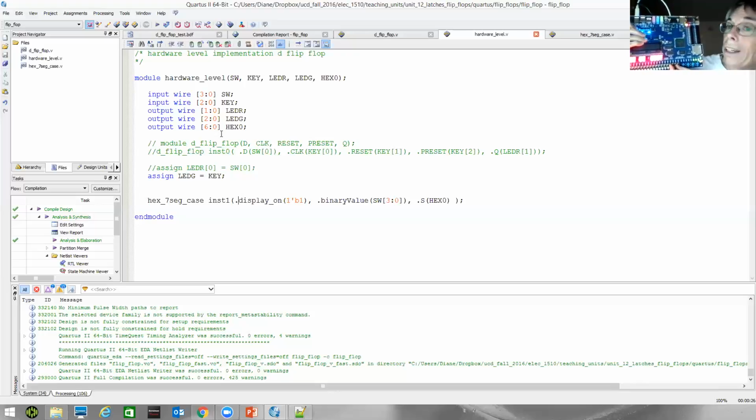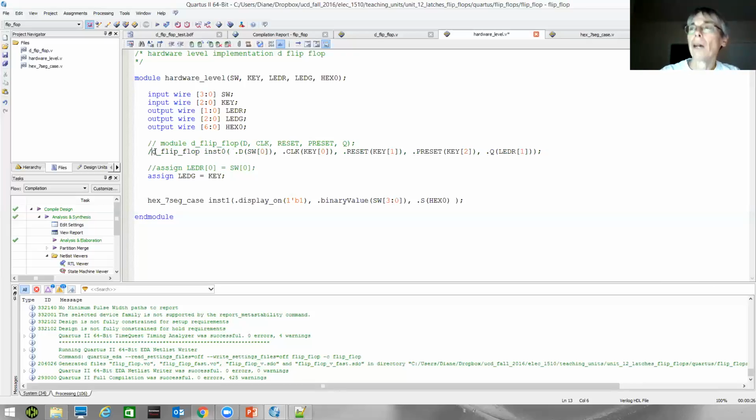It takes a 4-bit input, the way we wrote that circuit, in order to drive something. What I want to do now is drive the output of the flip-flop on here. I want to leave this display enabled, but pass the binary value in the flip-flop output. Here I was showing that on the red LED 1 before. I want to give that some sort of name.